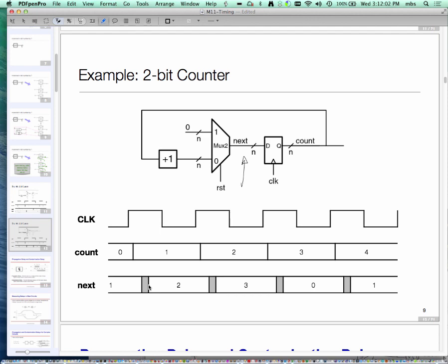So whenever I'm looking at more than one bit, if I send you 32 bits, let's imagine the following. Let's say I have 32 wires running from here to you. And I put a new set of 32 values on my end of the wire right now at some time t. But now imagine these wires have different delays. So by the time the bits reach you, the bits on the faster wire will reach you first. The bits on the slower wire will reach you later. So if you're observing your end of the wire, you will not see all the bits change together. You will see some bits change earlier, some bits change later.